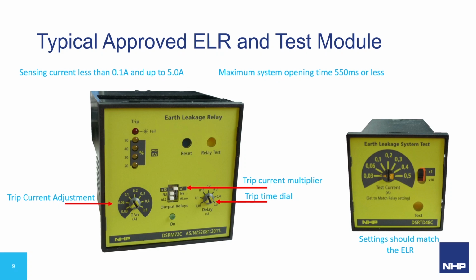The levels are set according to calculations based on plant and equipment startup needs, as well as the acceptable time for the existence of earth-initiated touch voltage rise within the installation. It's also to allow selectivity with devices downstream to trip instead of compromising the entire supply system when there is a localized fault.